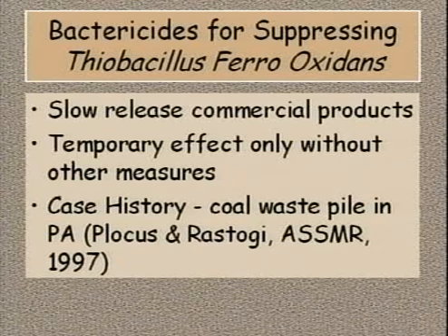An interesting case history involves the injection of a sodium hydroxide solution, which counteracted the pyrite acidity, and a bactericide through boreholes at an 8-acre revegetated coal waste site.